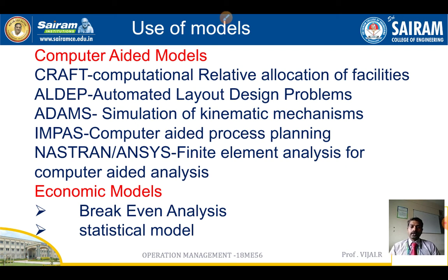ADAMS is a simulation of kinematic mechanisms. We also use ANSYS and NASTRAN, which are finite element analysis tools for models. Before producing a component, say we are designing a car bumper, whether it will withstand the load or not, we calculate with the help of simulation software. First we make the design and apply loads on it, apply the material type, and we get a decision on whether it is acceptable or not. So this is decision taking with the help of computer models.